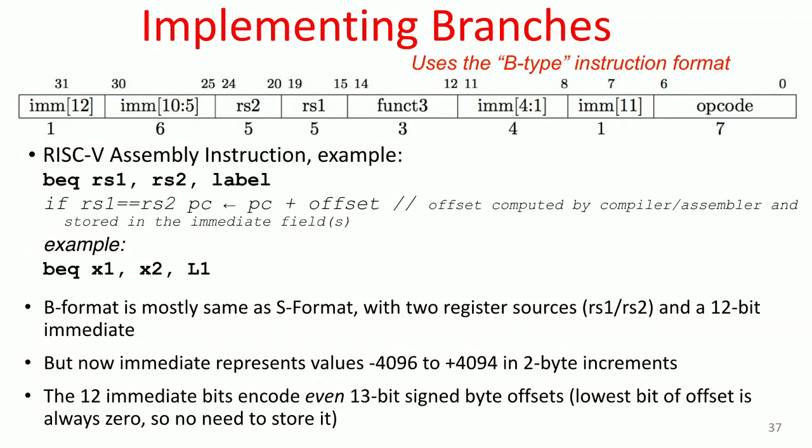There have been computers that have implemented comparisons that way. But we're not going to do that here because we're going to use the ALU. We only have one subtractor in our data path so far. We could add another subtractor. Subtractors are relatively expensive. They're more expensive than these equal comparators. Later we'll see we actually need greater than and less than comparators too. But for now, equal comparison is a lot simpler than a subtractor. And we're going to use the ALU for computing this offset. So we're going to assume we have a dedicated branch comparator.